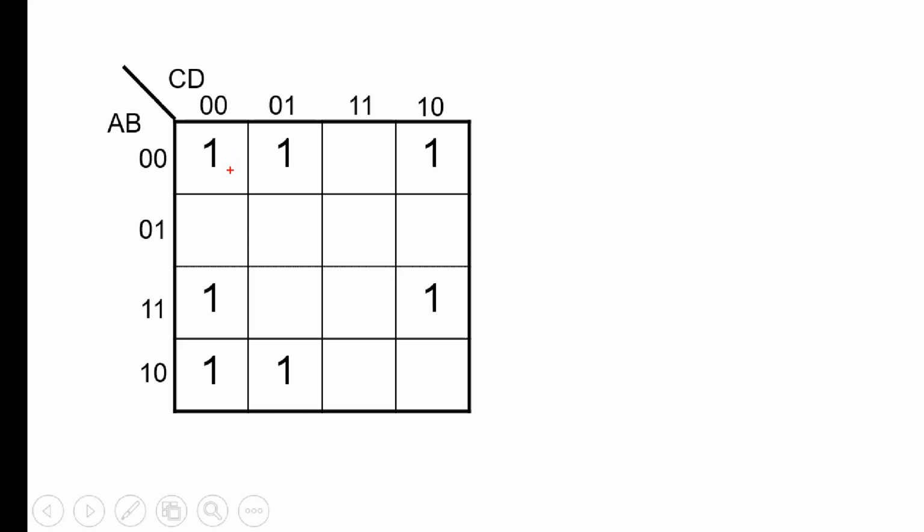How many cells should we select? 2? These two cells? No. You should select these 4 cells. It's better, right? Don't forget A, B, 0, 0, 1, 0. They differ by one bit, right? So you can group these and these together.